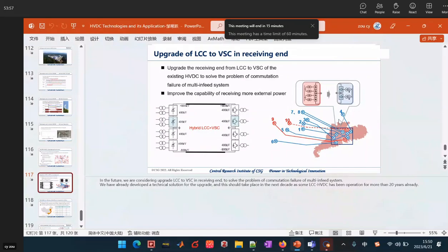If another HVDC is put in this area, we will recommend using VSC HVDC. But in the future, more HVDC systems are located in other areas. For example, here, the HVDC is not put here. There are not so many LCC HVDC put here. We can use more LCC here. We are avoiding using LCC here. Okay. Understood.